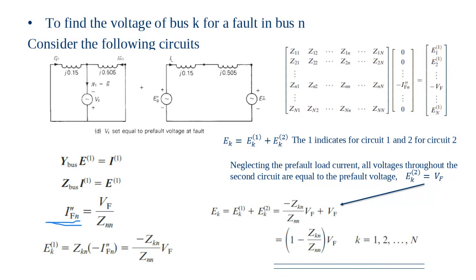If the fault is still there, it opens and then closes again. If the fault is still there, then the circuit breaker just opens. When the circuit breaker opens, no current will flow. So this will protect the equipment. It will protect the transformers, the transmission lines, the buses, and so on.